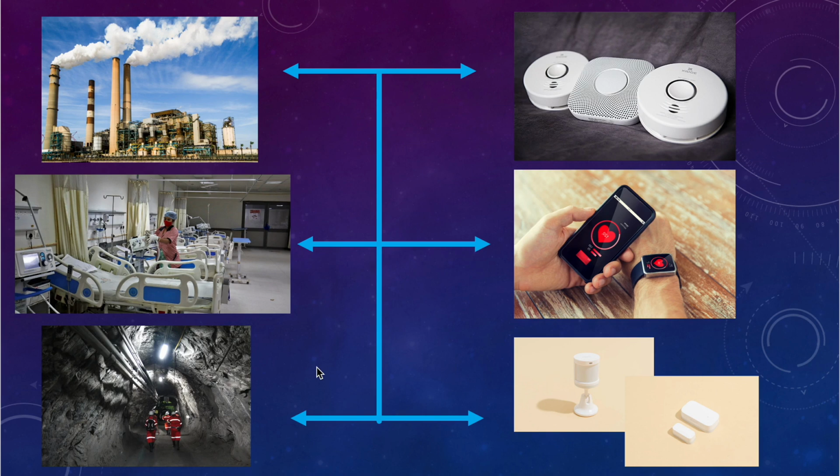If there are differences happening in the soil itself, these contact sensors can tell, because if this contact part is on one rock and this contact part is on another rock, and they have a small difference of change, that will be detected through these sensors and give early warning to people who are working in these mines. So yes, motion sensors and contact sensors can be used in mines in that way.